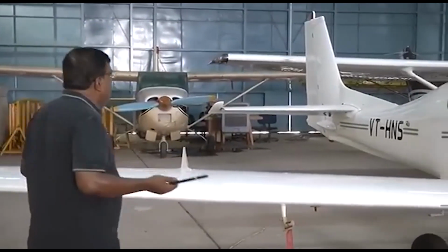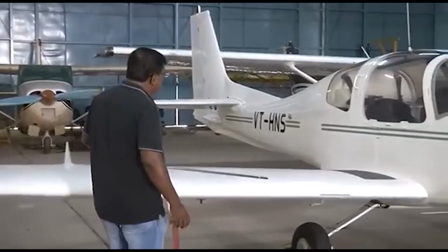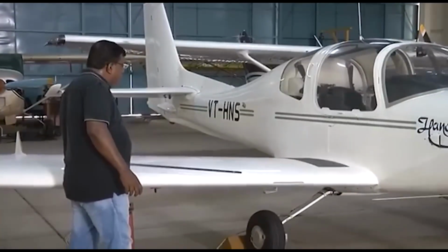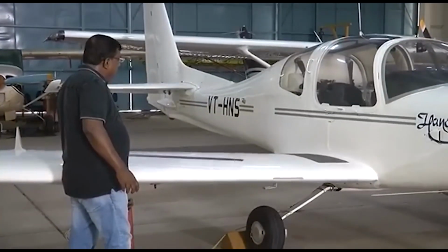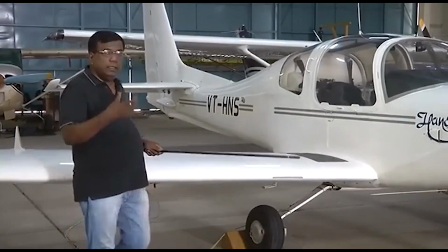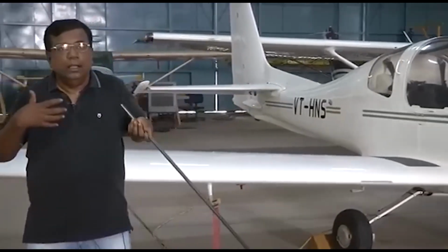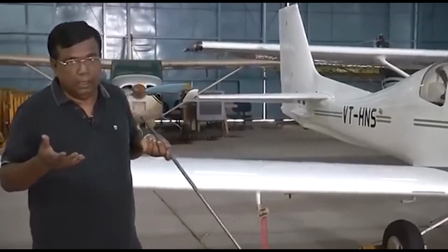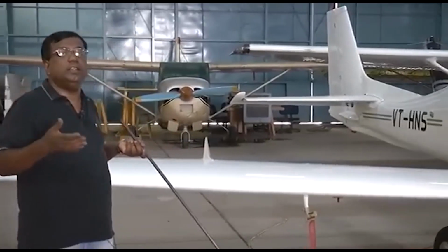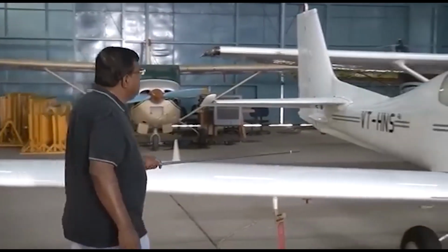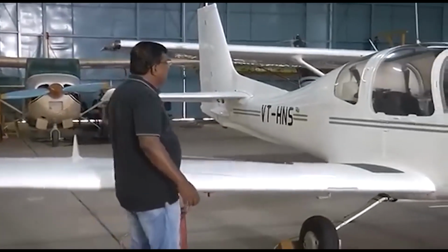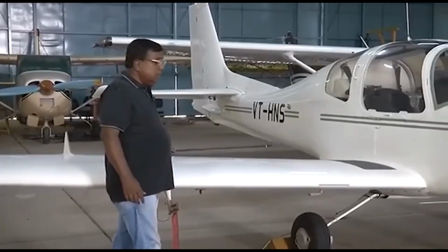So that boundary layer thickness could be, it's not a huge boundary layer for the wing, but it depends upon something which I call Reynolds number. Please understand, when a fluid is flowing over this, it has an inertia associated with the momentum of the fluid, right? In textbooks, they call it inertia force. So that will try to ensure that it remains in the state of motion.